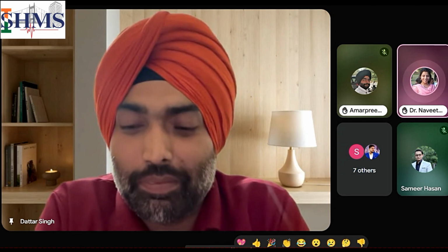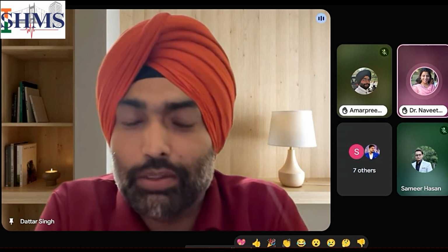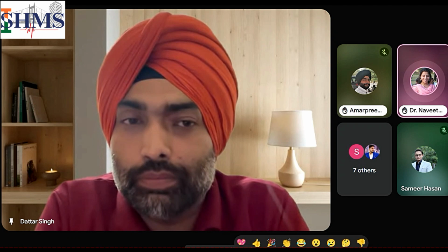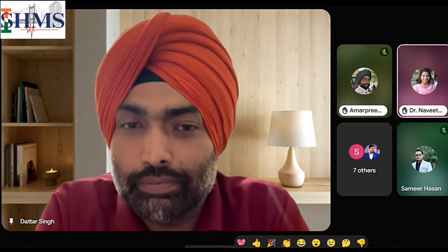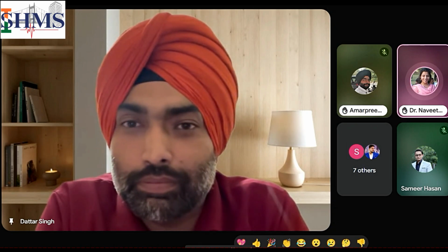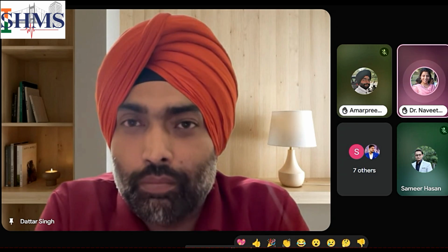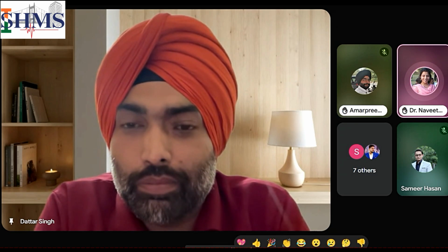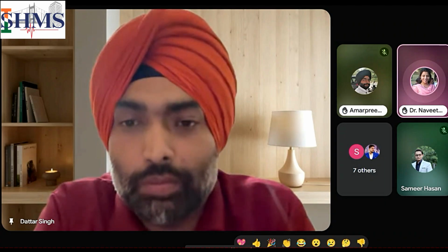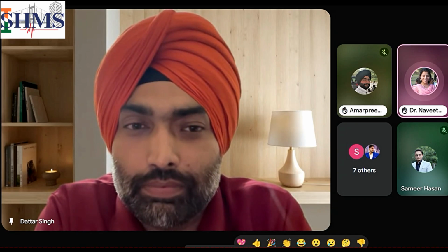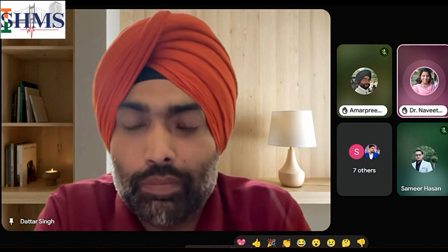Wonderful. Dattar, I just have my own doubts, not really from your presentation, but regarding this modal analysis. When we are trying to capture the natural frequency in the field, if we have not done the numerical analysis of the structure, is there any way to get some idea whether the results we are getting are correct or not? You have been able to find almost 3, 4 to 5 modes, but in real conditions, when we tried it for concrete structures, we could find hardly the first or maybe at most the second mode. Is there anything wrong we are doing?